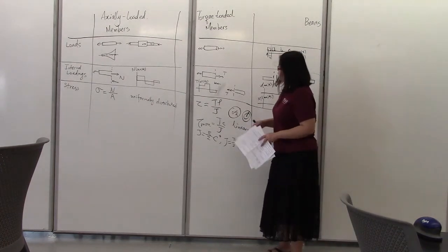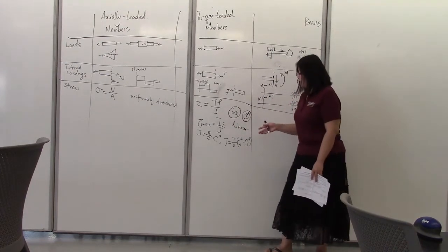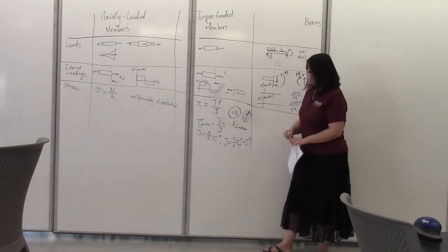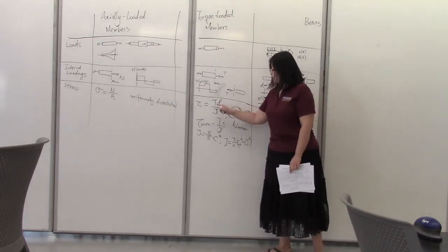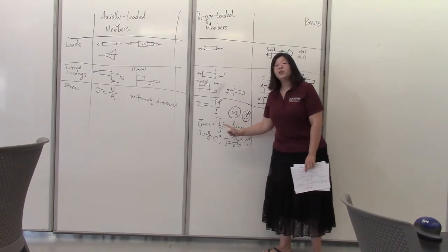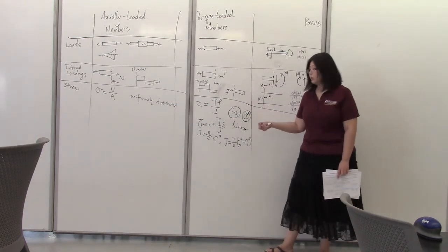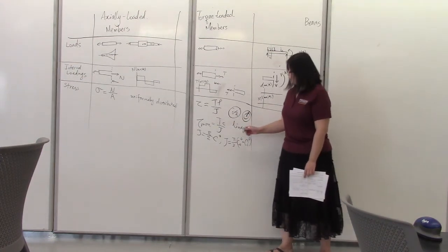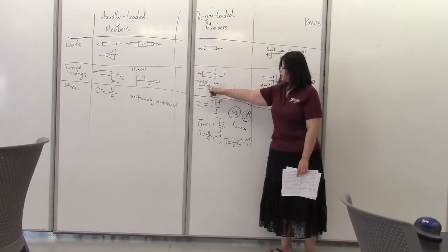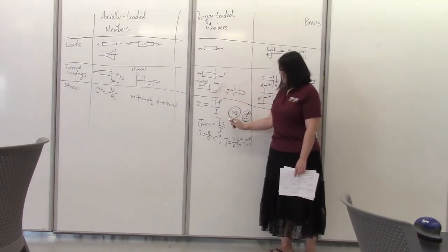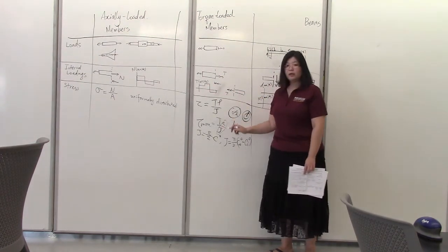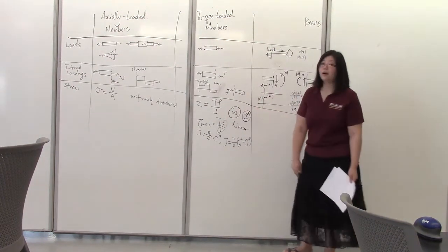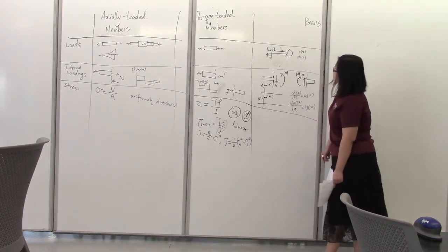Now, it's not very clear sometimes where exactly the maximum shear stress would occur along the length of the member, because that depends on T, c, and J. All three could contribute to having a maximum shear stress. So sometimes you'd have to check which section has a larger T and which section has a larger c over J ratio. So the combination would give you the maximum for the entire bar. All right, so that's for torque-loaded members.